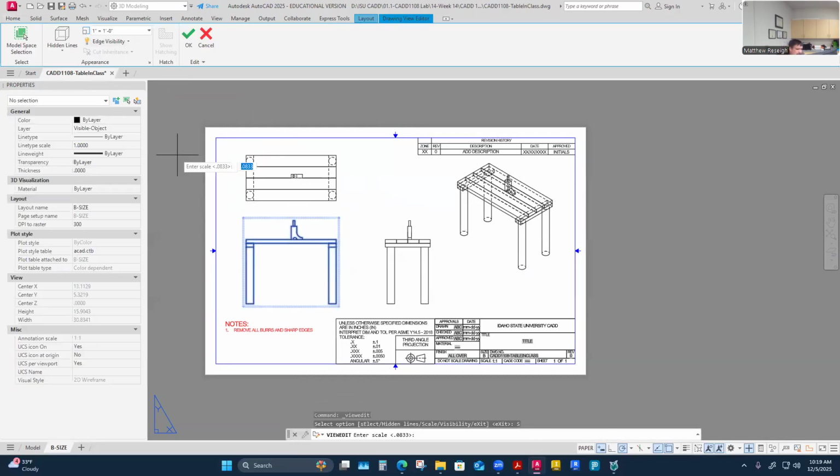So scale is where it's a decimal scale. It just assigned this scale 0.083. On a drawing, I might choose to make this something that's a little easier. I would want to put this scale on my drawing, so I could use that as the scale, and I could come down here and say it's like 1 to 0.083. That would be fine. Whatever scale I place these at, or if I change them a little bit, I just want to match them in my title block eventually.